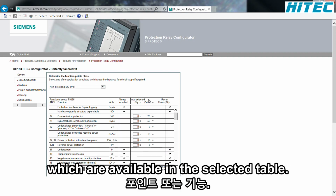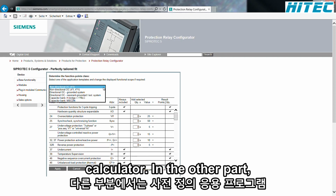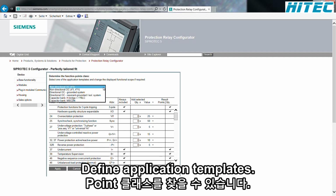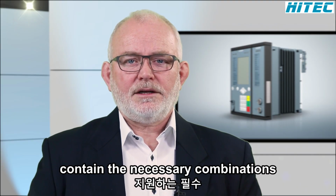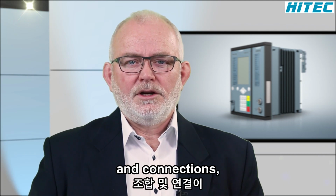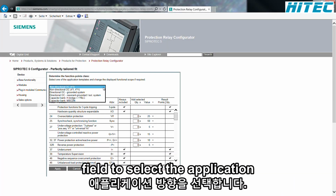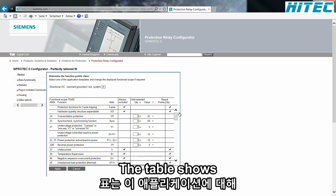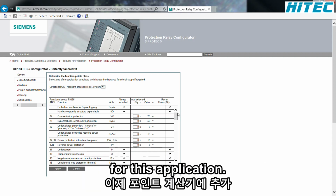All functions which are available in the selected SIPROTEC5 device are listed in this point calculator. In the upper part, you will find function point classes with predefined application templates. These templates already contain the necessary combinations and connections which will support your final configuration. We are using the scroll down field to select the application: Directional overcurrent, resonant, grounded, isolated system. The table shows a basic selection of all activated functions for this application.